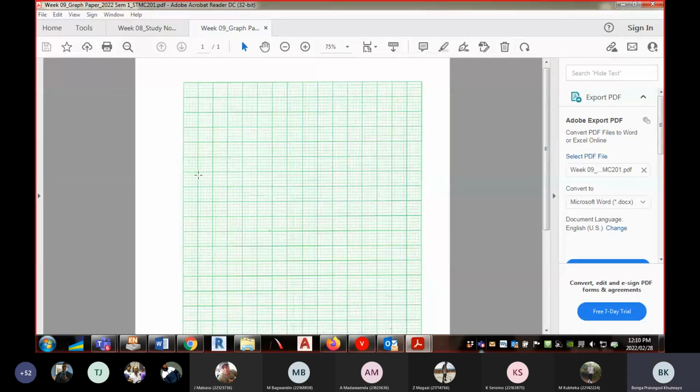You need to draw these diagrams to a reasonable scale. At the end of the day, someone else should be able to make sense of what you've drawn. So they need to be reasonably clear, labeled correctly, and neat. You need to look at your reactions and then decide on the scale you're going to adopt.